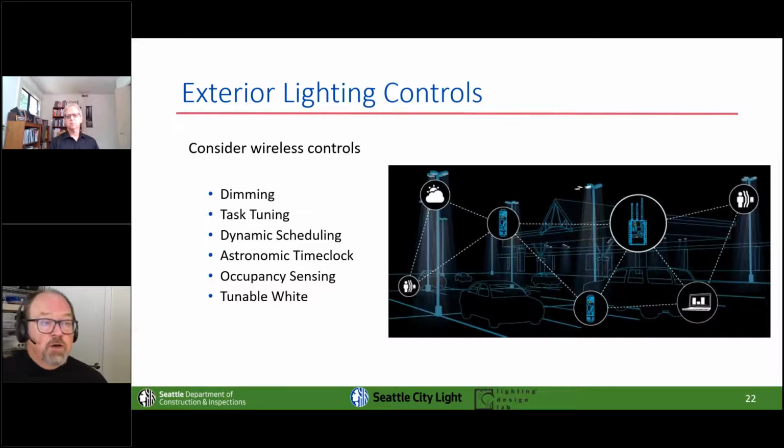Also, imagine, you're essentially looking for movement of background infrared. Well, the human body is 98.6, right? We had some 98-degree days this summer, right? So if the human body is similar to the background radiance of the space, it's not going to catch you. Now, there are advances in microwaves and LiDAR and a variety of other things. I'm going to tell you that probably within the next 4 to 5 years, I would be shocked if they didn't have the outdoor occupancy sensor challenge licked. Okay, we'll be looking forward to that.